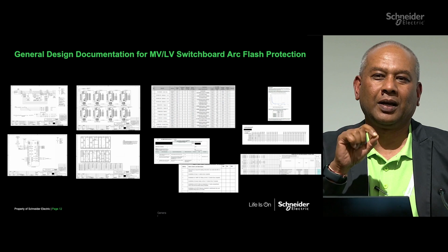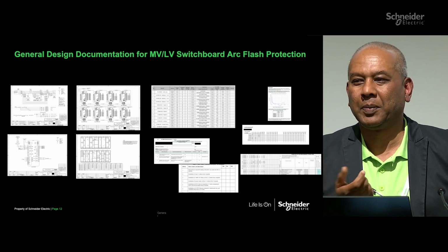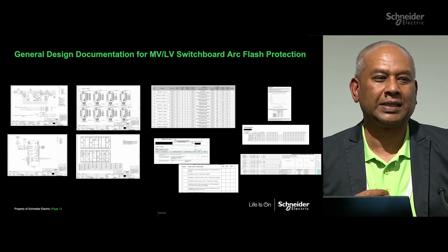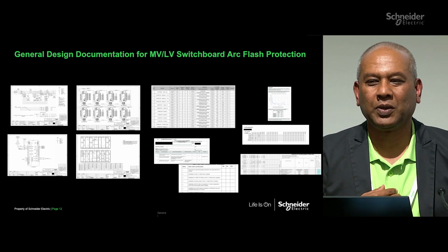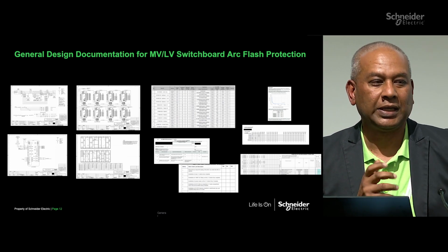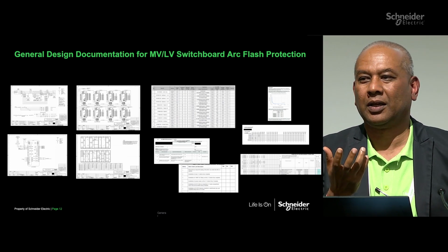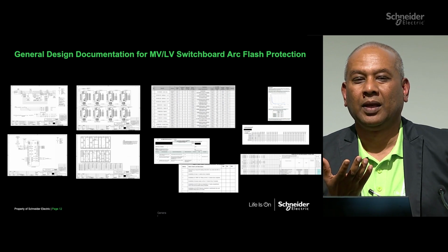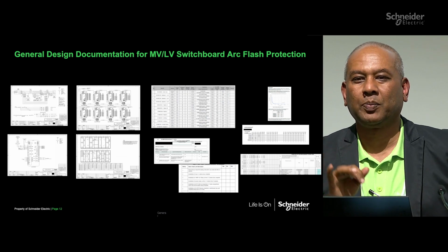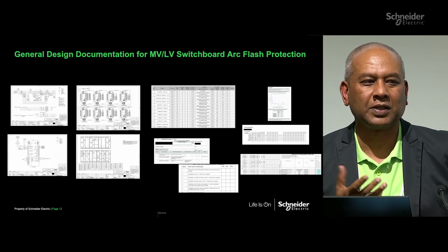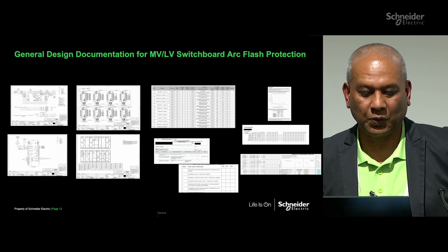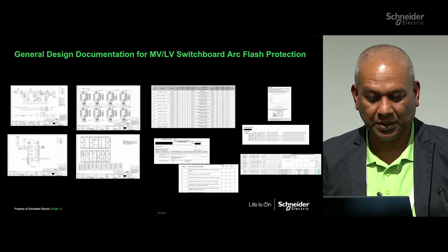So that's only locked in and as-built after implementation. During commissioning, we need to send some qualified people who know where to locate sensors in Schneider boards. Of course, we know our boards, but with third-party boards, quite often we have to find the best location for the sensor, which is the location that won't be invisible to arcing, covers the maximum zone, and is not blocked by other hardware. It needs a bit of skill, which can be trained to other people, but quite often for the first few, we deploy our own team to make sure it is all done correctly.